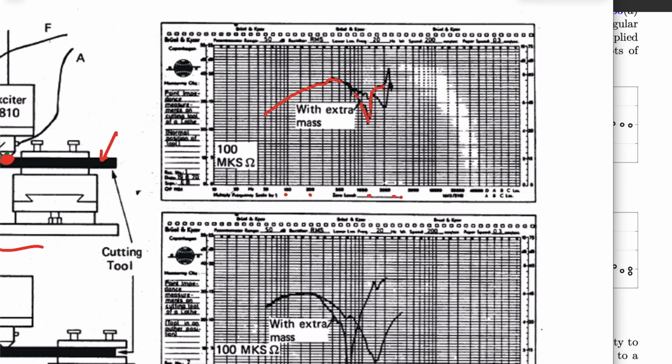Compared to, for example, that analog meter that we're going to study in the lab, where we're down at about 5 hertz as the highest frequency, when you're making measurements like this, you're using really high frequency measurements. Accelerometers and so on have to have high bandwidth, right? But look at what you're seeing. You're seeing peaks. You're seeing what's called anti-resonances and resonances, and it says something about two different cases.